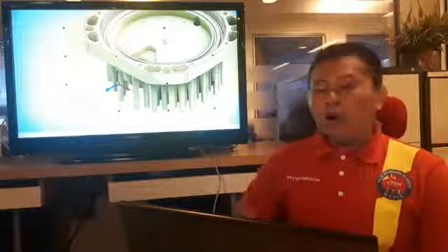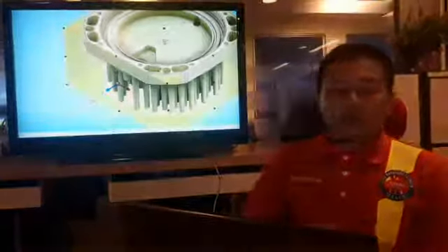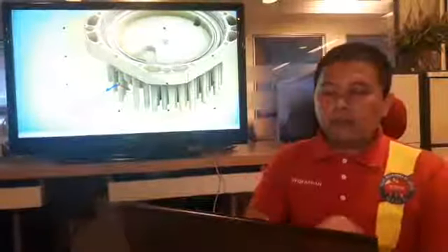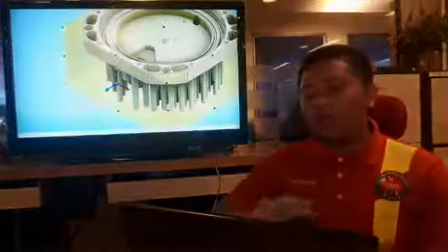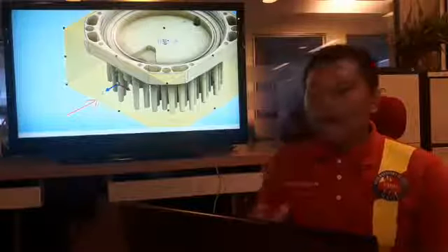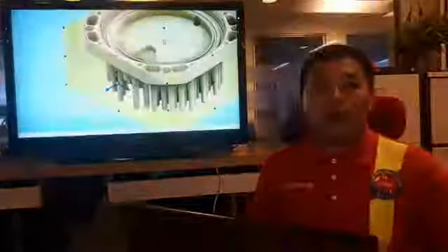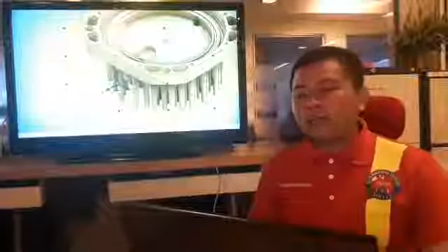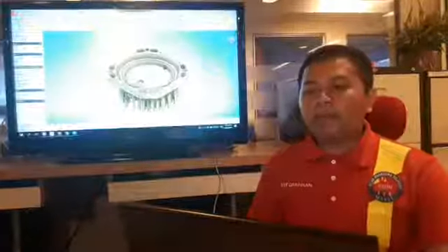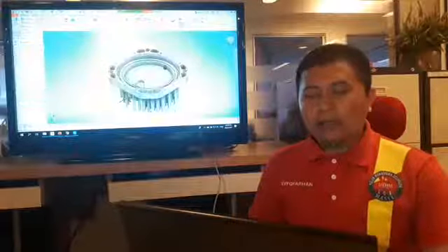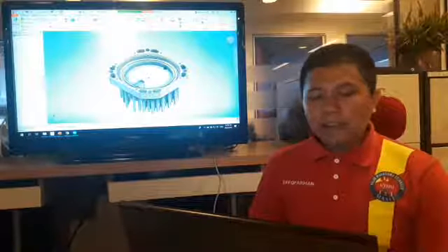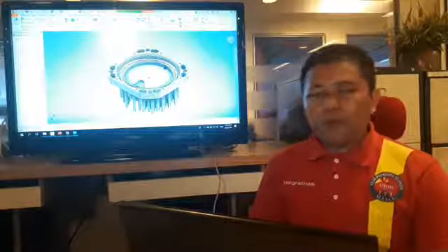So if I do drilling, the drill tool will start from the Z direction. I need to change it to make sure the Z direction starts from the correct way. For example, if I use a 3 axis CNC machine, I need to make sure the tools start from the top.